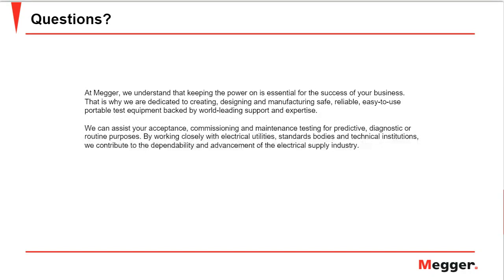Because for newer transformers, you are supposed to require that information from the manufacturer. But you can get some guidance on how to produce the damage curve from the IEEE guides, and it will depend, of course, on the type of transformer that you have and the classification of that transformer according to those guides.